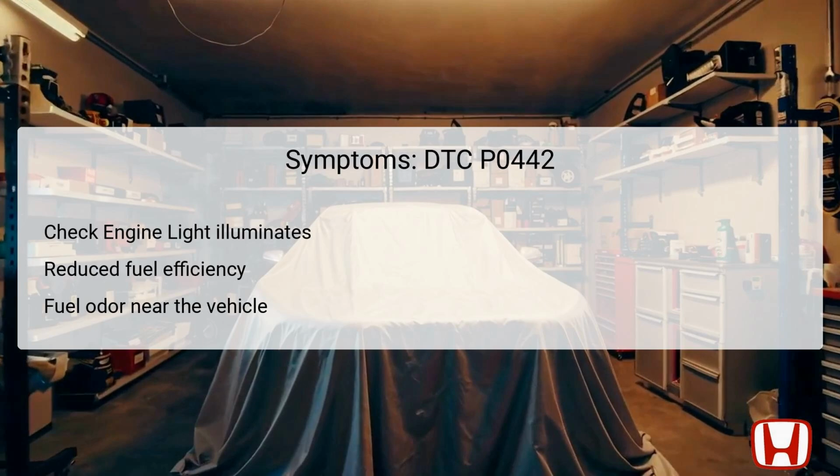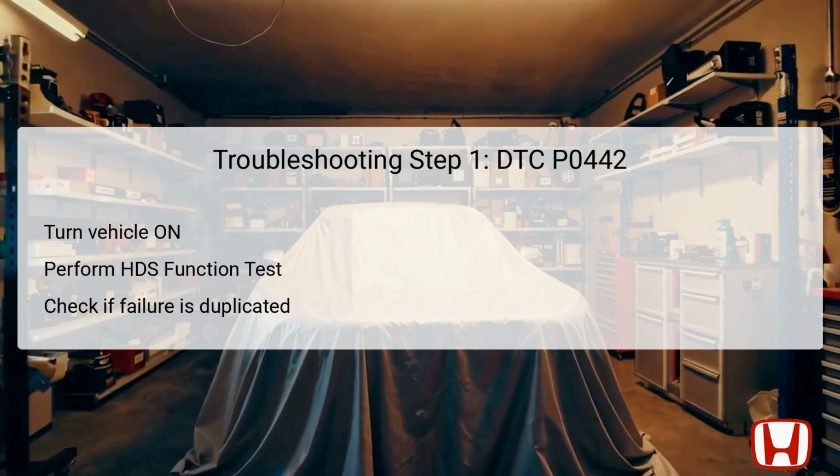The first step in troubleshooting DTC P0442 involves turning the vehicle ignition to the on position, ensuring that all electronic systems are activated. Following this, a comprehensive function test utilizing the Honda Diagnostic System, HDS, must be performed.